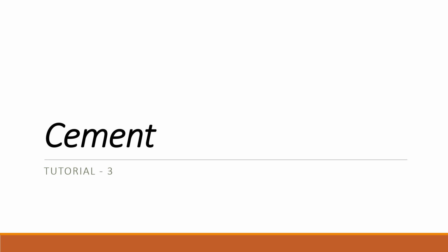So last week we discussed the aggregates, am I right? So this week we are looking at cement. So cement is the binder that we use in the rigid pavement to bind the aggregates together. And when we add water to cement, cement is reacting and that will become hardened. So that is hydraulic cement, but we have non-hydraulic cements as well.